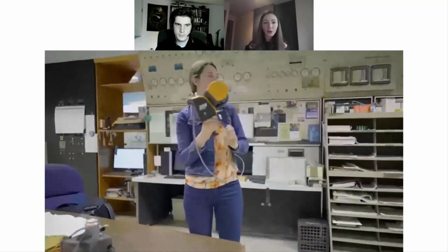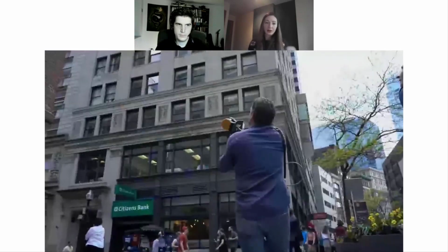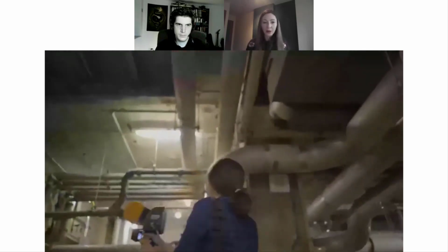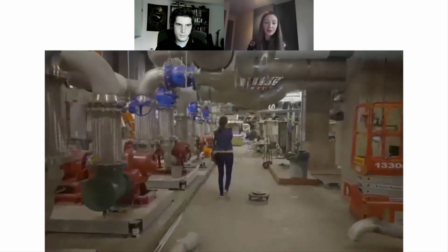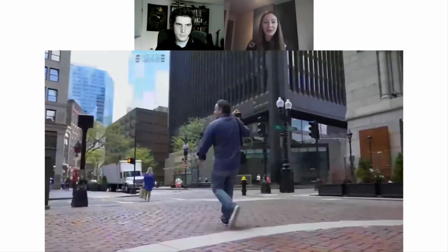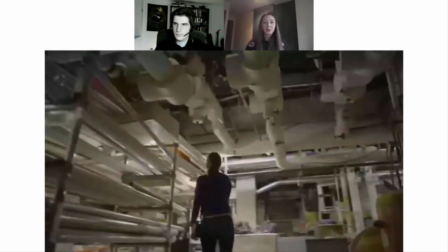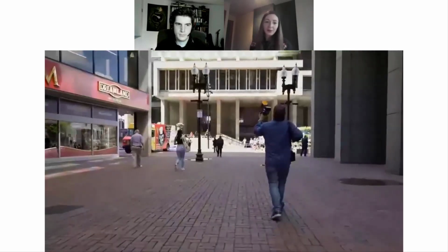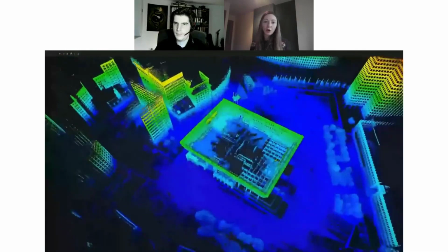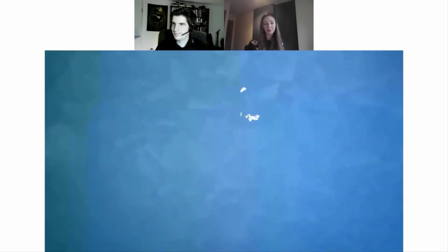Here you can see the operation itself is quite easy: 2 buttons to turn the scanner on and just walk around the environment, where moving people and vehicles do not matter, as long as you have static features like buildings or furniture or boiler rooms inside. After data capture, the data was first merged in GeoSLAM software, and then Draw was used for sections and layouts and RCP export to finish the BIM modeling of the building.